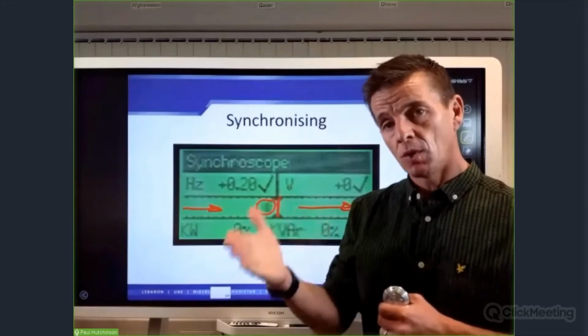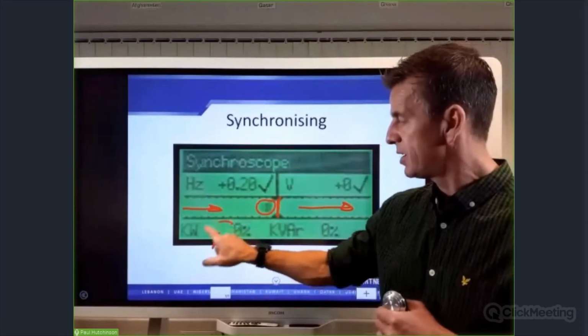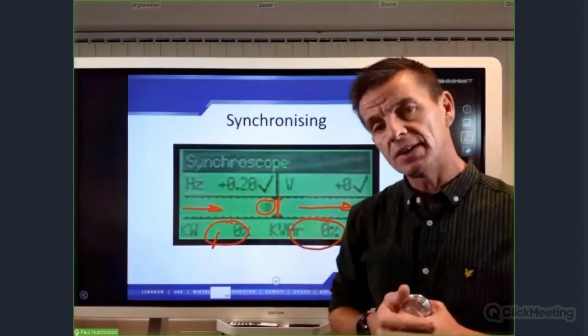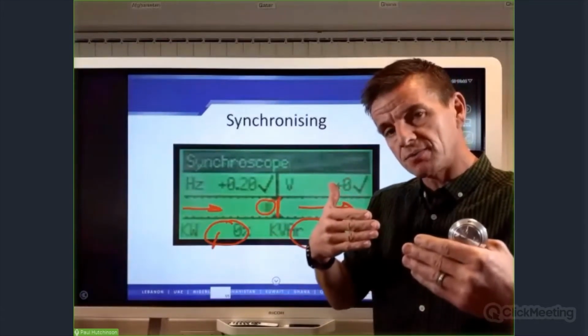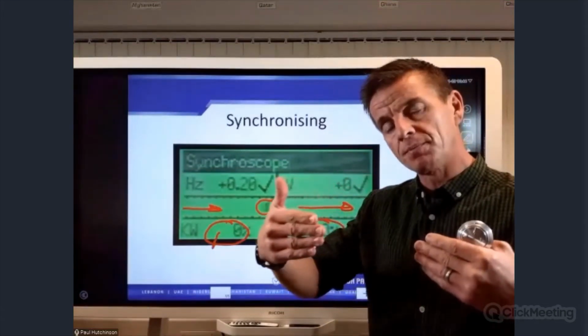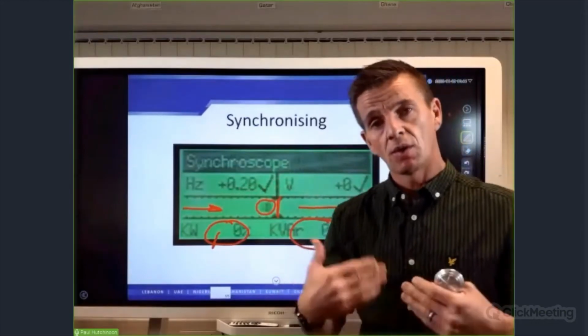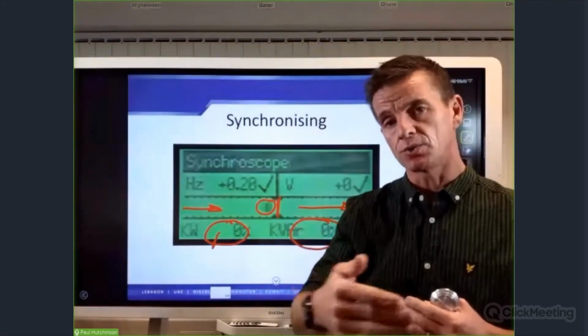And at which point, it will issue a breaker close command, okay? And at that time, once the breaker has closed, we'll start to see information here and here. So once it's in sync, then it will start to ramp up with the load that's on the system. Again, depending on where or how the configuration settings tell it to go to.